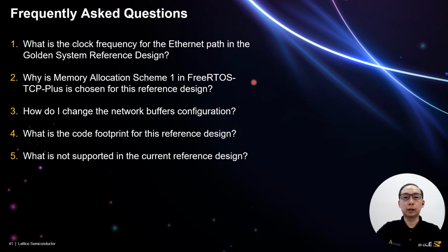Since the network buffers are allocated during build time, the runtime performance is better in this case. And also since we are using the external memory, the LPDDR4 memory, we are not constrained by memory space.